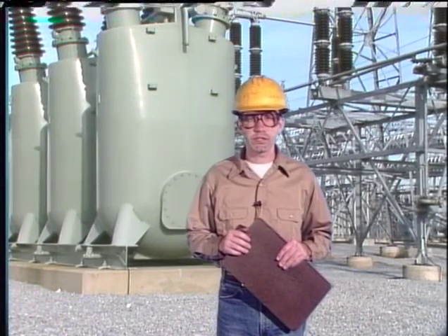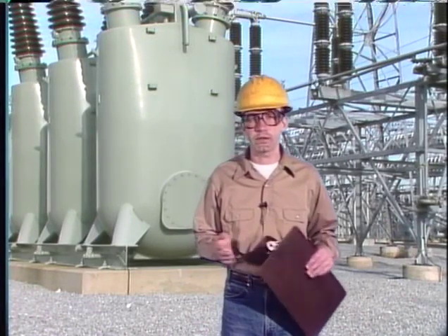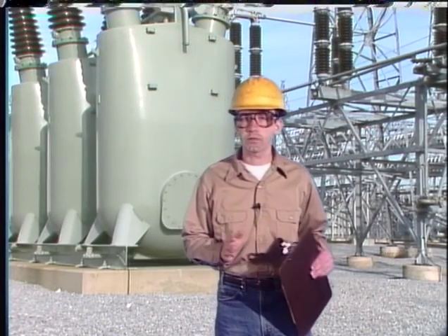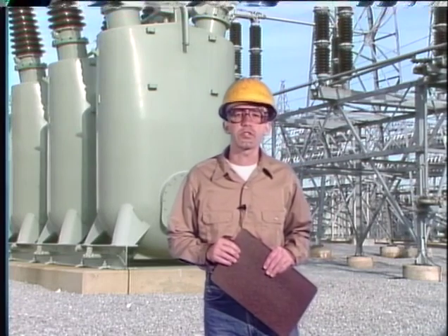Internal breaker components need servicing from time to time to ensure that they will continue to extinguish arcs and make and break circuits when needed. But a breaker cannot reliably extinguish arcs unless its operating mechanism also works properly. So servicing a circuit breaker's operating mechanism is just as important as servicing its internal components. In this part of the program, we're going to look at some general maintenance that applies to most breaker operating mechanisms. Then we'll look at some specific tasks for solenoid and motor spring operating mechanisms.